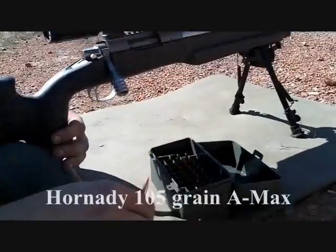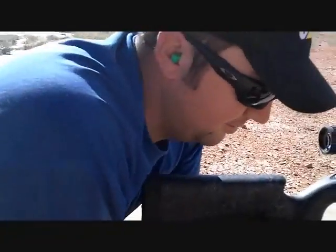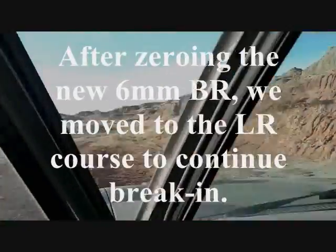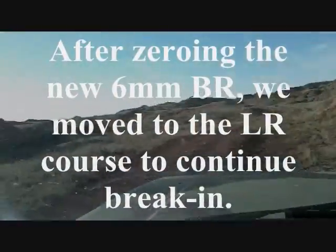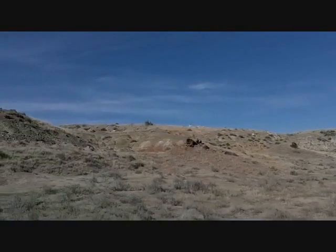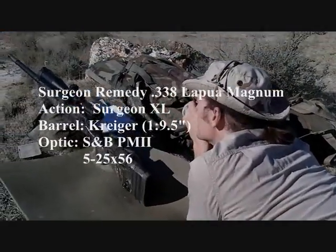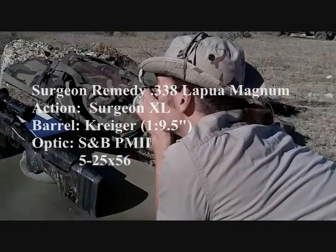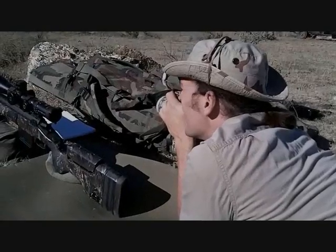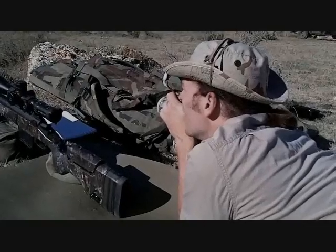Just go out and shoot at some paper and see how well it's really shooting. If you are having problems, that's an indicator that you have harmonic and vibratory inconsistencies. And then you can go through and start eliminating these problems. So your number one thing is basically the bedding of your stock. You want to make sure your action is completely solidly mated to the stock. You don't want the barrel to have inconsistent contact points, so that the whip action of your barrel is absolutely the same from shot to shot. You want to make sure that the lockup of your bolt lugs is consistent from shot to shot as well.